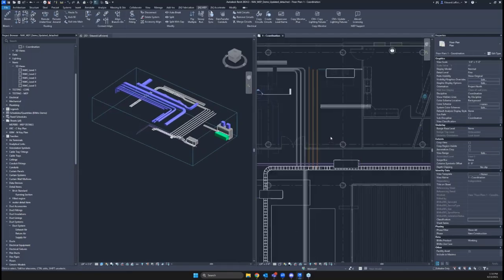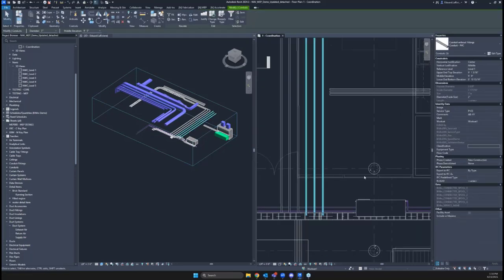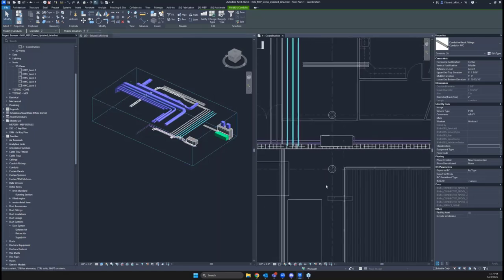Now, before we get into something new, I'd like to go talk about something old, those elbow tools. They're pretty cool. Elbow up and down is pretty neat. But what about maybe routing a rack through a building? Let's take a look at these 3 conduits right here. Maybe I want to grab that whole stack of conduits, and I'm going to use some keyboard shortcuts here for my elbow commands and for my move command, Revit's out of the box move. And maybe I want to route this rack through my building.